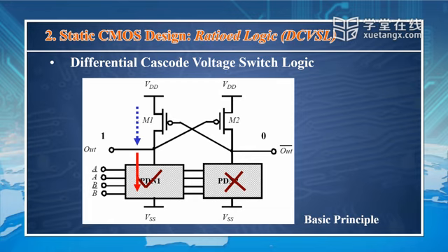If we can make sure that the pull-down network here is stronger than the pull-up network here, stronger than M1, therefore the Vout will decrease a little bit, then turn on the transistor M2. Okay?